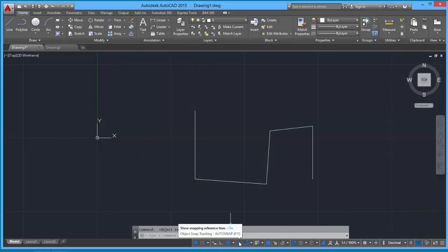So then we come to these two. We've got object snap tracking and we've got object snap. Now I'm not 100% certain what object snap tracking does. It doesn't seem to change much if I turn it on or off. But anyway, what is useful is having the ability to track. So depending on some track settings, if I wanted maybe to draw a line that was the extension of this and then to tie in with my polar track sets, then I get these sorts of intersections. So it's a very powerful way to draw objects in AutoCAD.